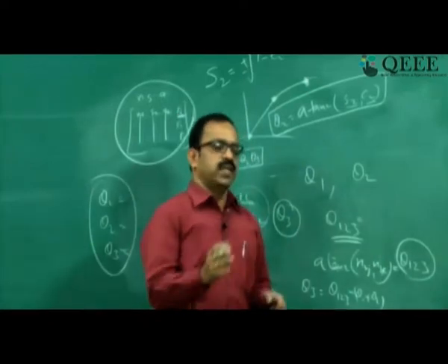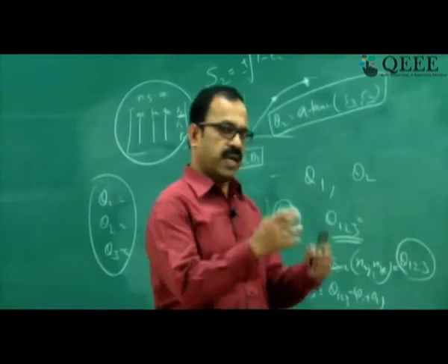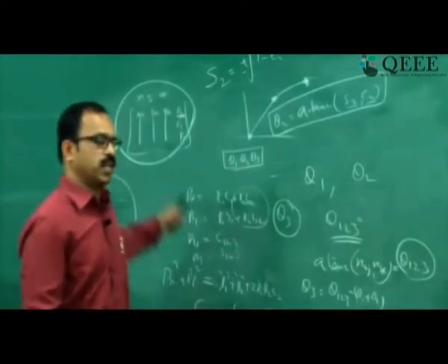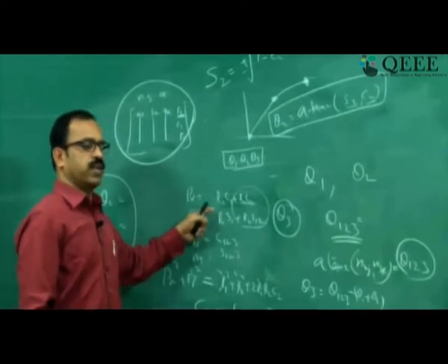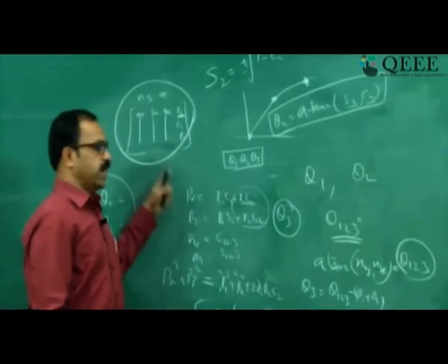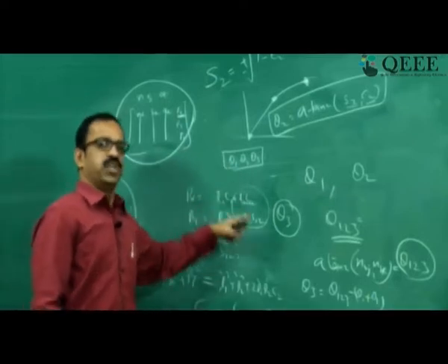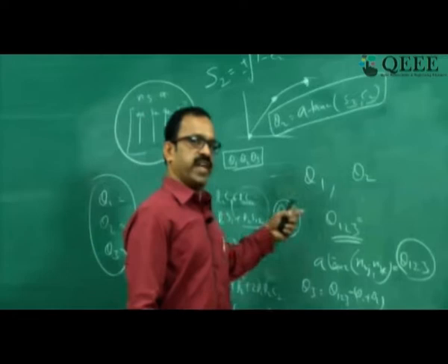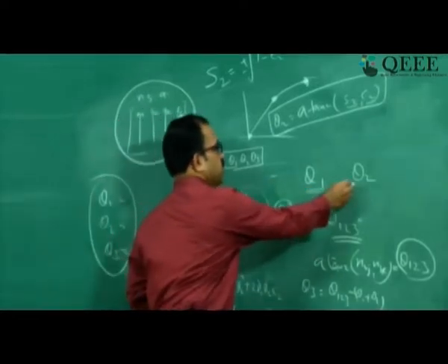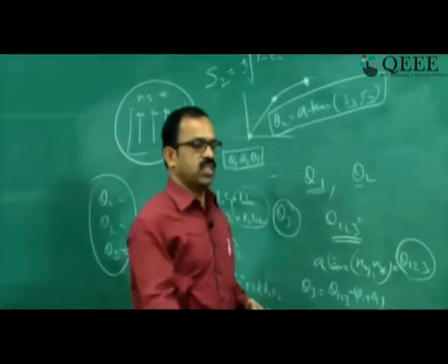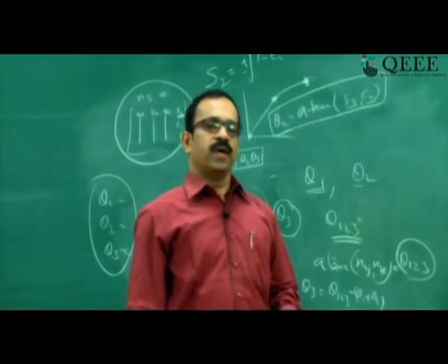So you can see that we start with the forward relationship and write down the 12 equations, and then solve those 12 equations in an algebraic way using algebraic relationships and the tricks for solving them, by substitution or by squaring and adding, and try to get a relationship to solve for theta 1, theta 2 and theta 3. So this is the way how we solve the inverse kinematics problem for manipulators.